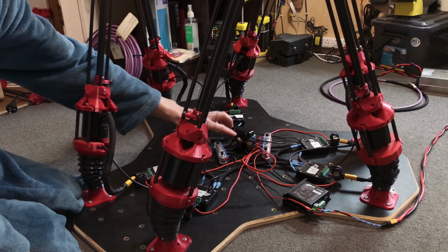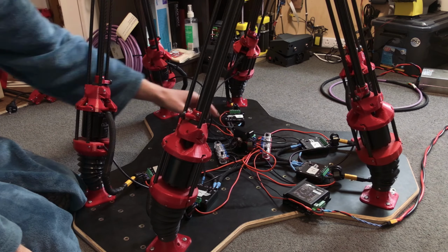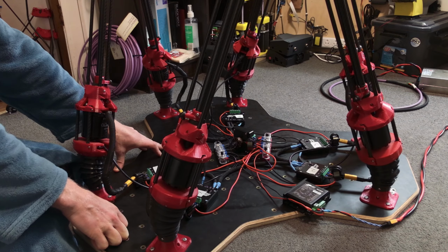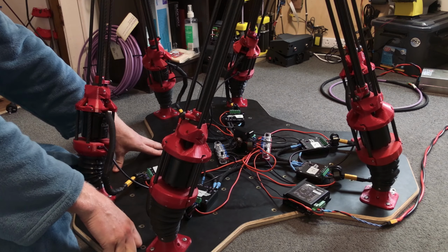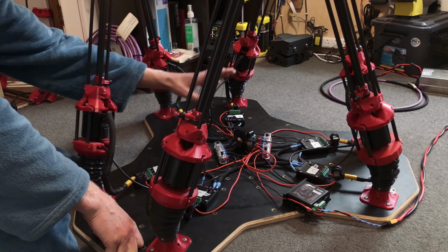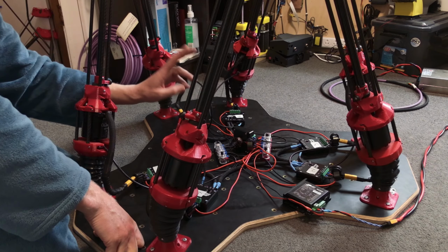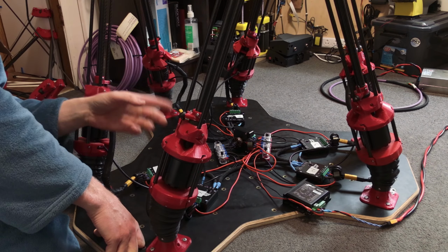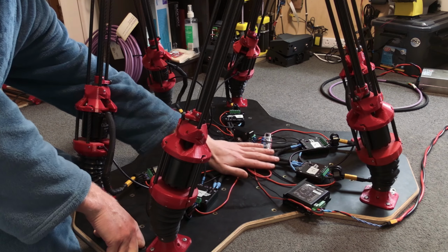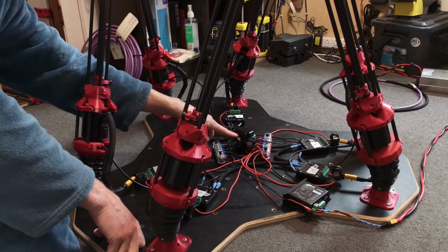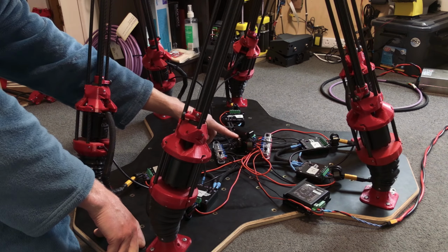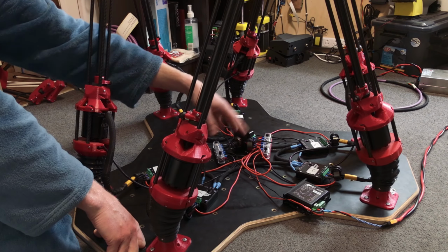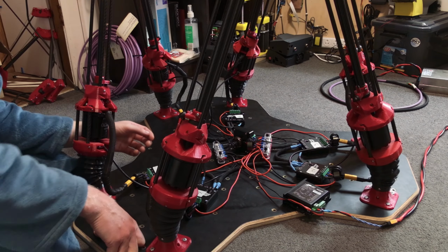So I'm considering making a quick release system to really easily separate the motor from the ODrive, so that way I can really push it, and if it does catch fire or something, I can just quickly rip it off. But for now, I haven't done that testing, and so I've got 2 options. One option is to get some sort of buck converter to convert from the 45 volts of the main bus to the 21-ish volts of the hand motor. But I don't really like that because it's just another thing to make a mess around the base.